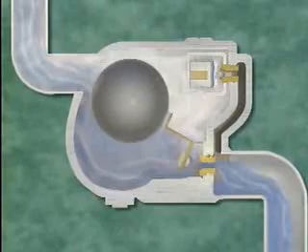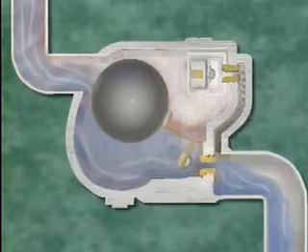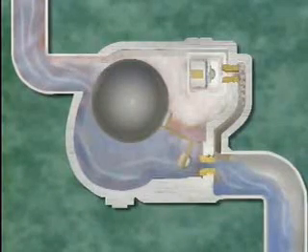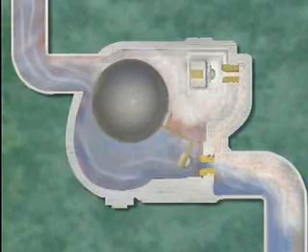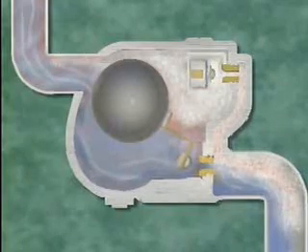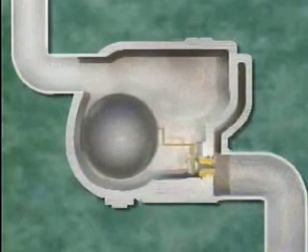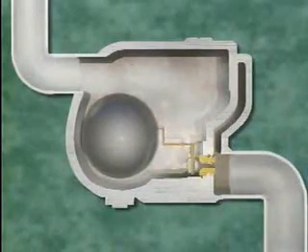The buildup of air and gases in the trap lowers the temperature and eventually causes the bellows to contract, which opens the vent valve. Then, the air and gases are discharged through the trap outlet. The reaction of the bellows to temperature changes enables air and non-condensable gases to leave the trap and keeps the trap from becoming airbound. Air binding, or becoming airbound, is the condition that results when air fills a trap, closing the trap valve and keeping the trap from operating.